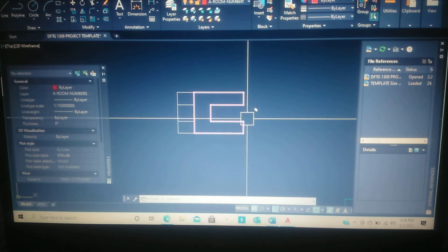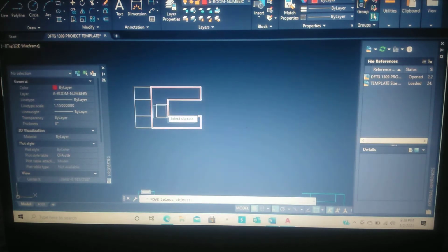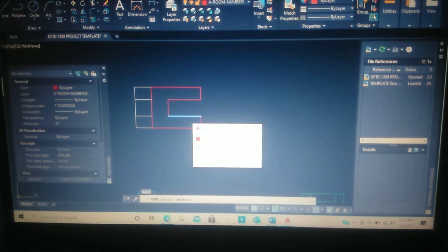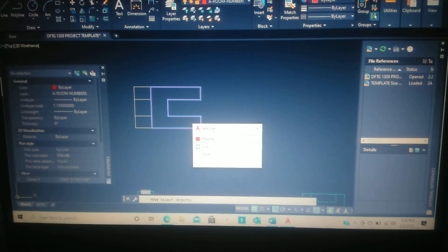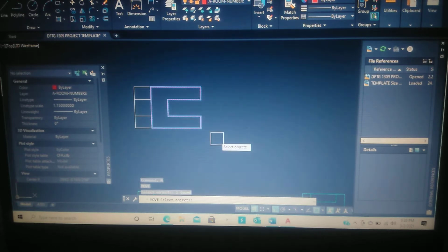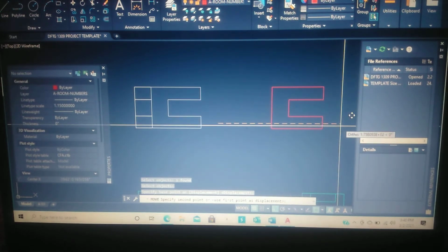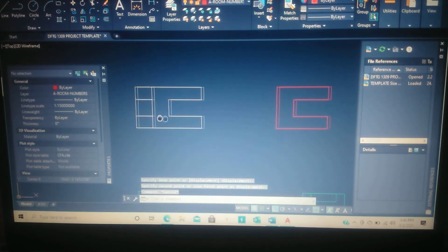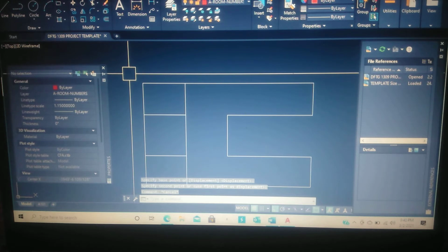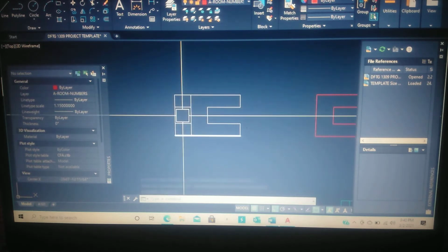So let's go ahead and take this, select the polyline, and it'll ask you about the selection. It's asking you, do you want to select the line, you see the blue line highlighted in the background, or do you want to select the polyline. So click polyline. Right click and then move it over. Okay. Now let's P-line this part 1 up.